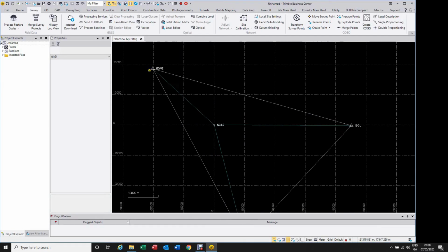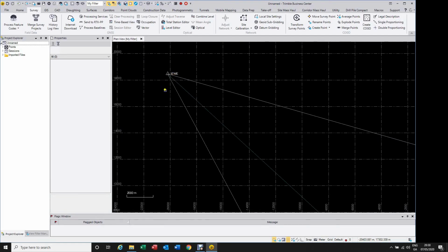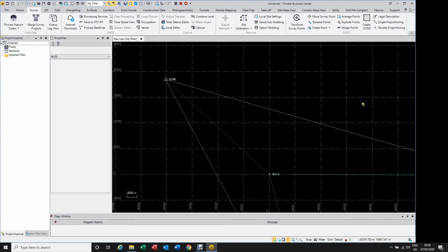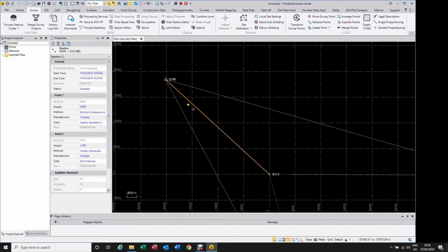So just to imagine what's happening here. The measurement was carried out during the same period of time. This baseline has 2 points at its ends, with 2 observations. Each observation is basically 4 hours, this one maybe more, but only the shortest time determines this calculation.